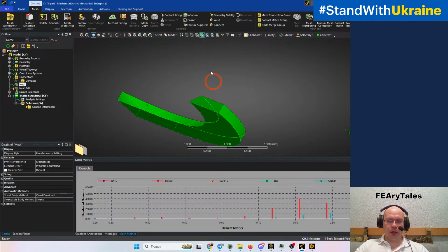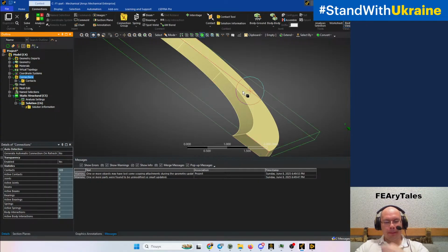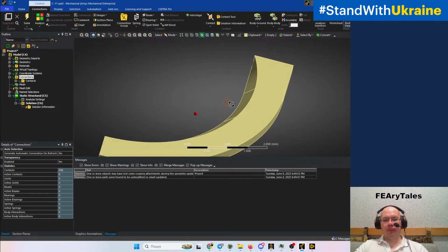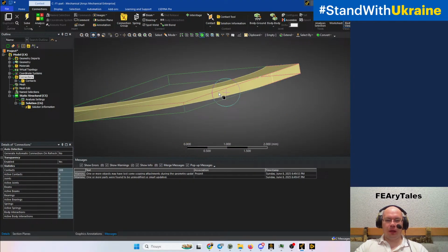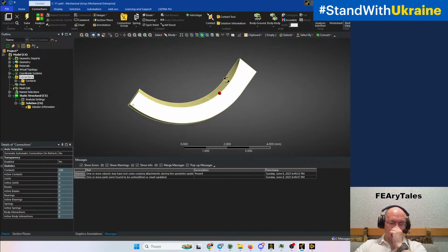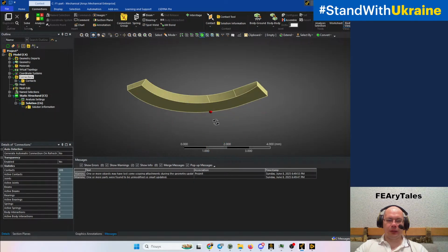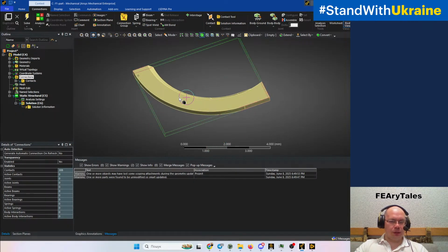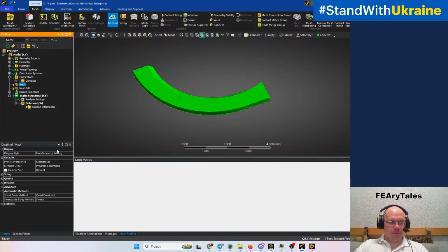Hide all other bodies. The reason is that we have a couple of additional edges here. We have two faces here, and we have three faces here, so it's better to split this object in those places. But we can try to create a multi-zone.